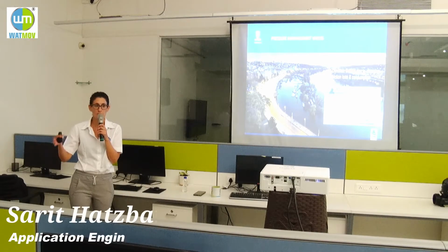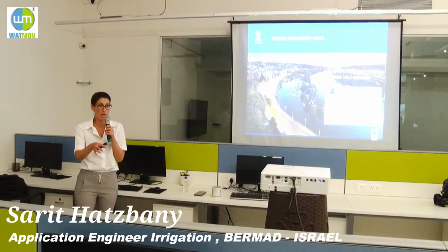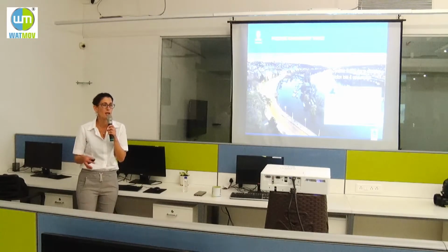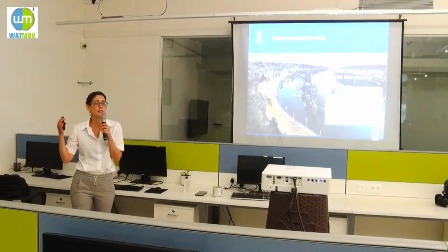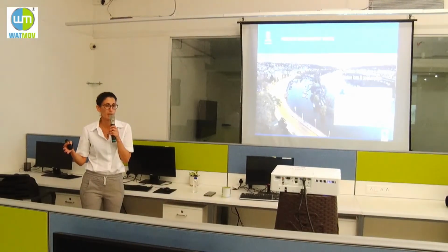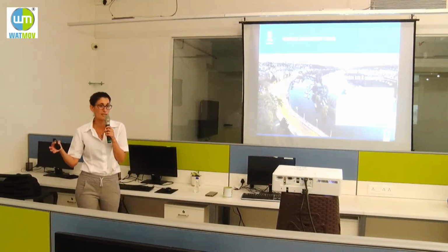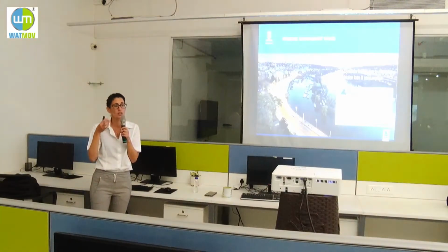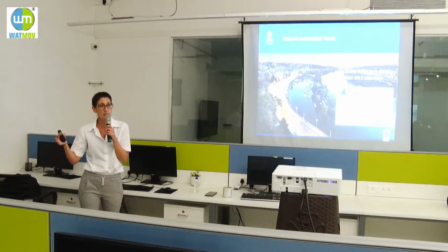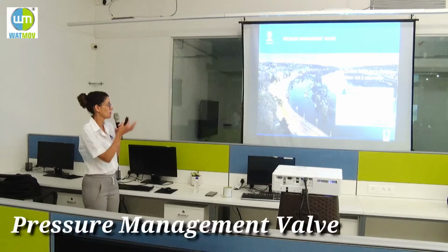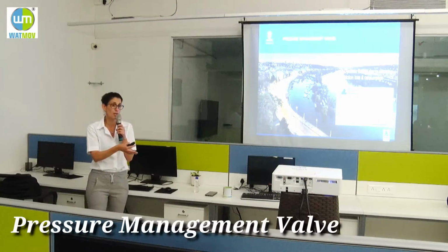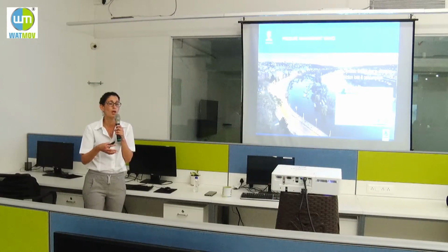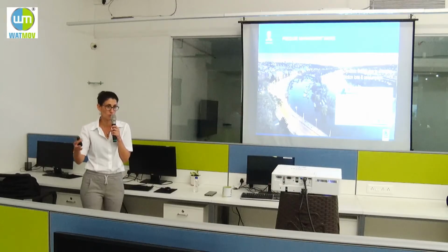More simple pressure reducing, which is the proportional PRV, okay? And now we will talk about more sophisticated pressure reducing. Could be more sophisticated, because if we want to dynamically change the setting of the pressure reducing, this is something we can apply, and it's one of the solutions that we give when we talk about municipal water delivery to households, okay?